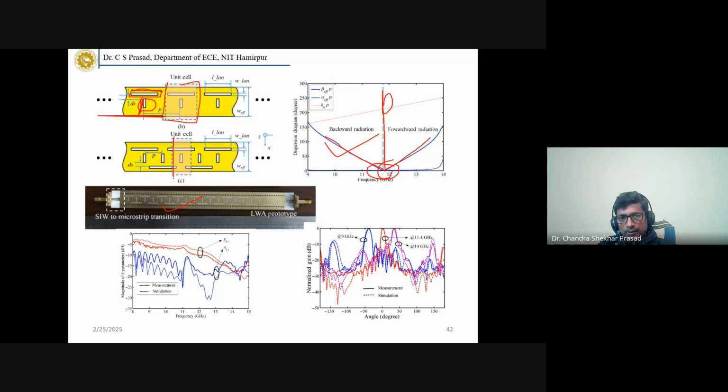If you go through this paper and see the input impedance, this is all about impedance matching. You can use different impedance matching techniques and match the unit cell impedance, or the Bloch impedance, which should be equal to that of the unperturbed line. Then we will not have the open stop band phenomenon.